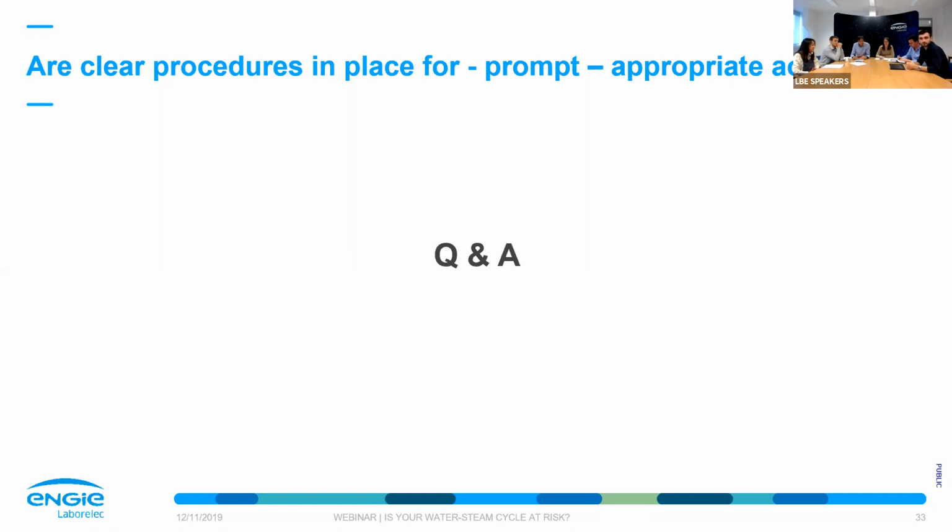Okay, thank you. Another question is, can we detect condenser leakage by testing chloride? We currently don't have a sodium analyzer. And what is the limit? Yes, to detect the condenser leakage by offline analysis is maybe not the most recommended way, because when you do offline analysis of chloride, it's already tough to have reliable results.